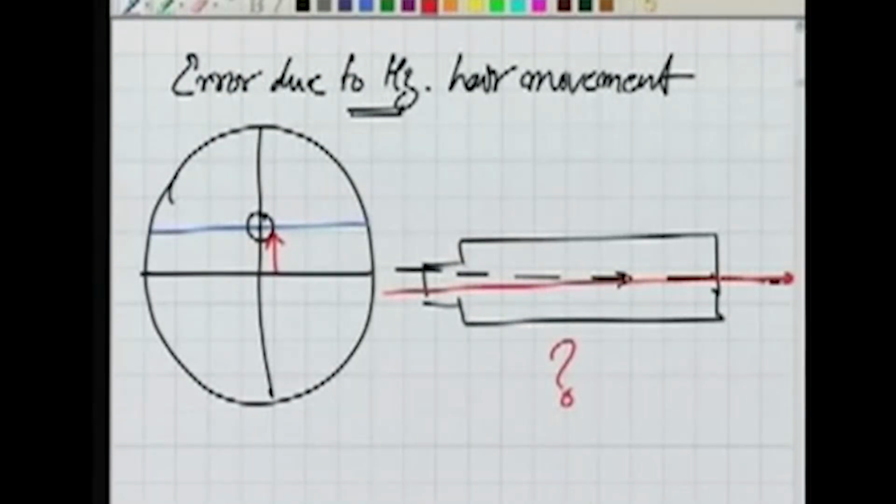To eliminate it, now we will see here in the instrument itself. Let us say right now the center of the crosswire is here. The face is towards my right. Now I change the face. In changing the face, just follow me. Where I am holding is the center of the crosswire. To change the face, it will stay like this, and that's the center of the crosswire, and the center of the crosswire comes down. Well, now the face has changed, but in order for me to observe, I will rotate it like this, and now the crosswire center is here and here.